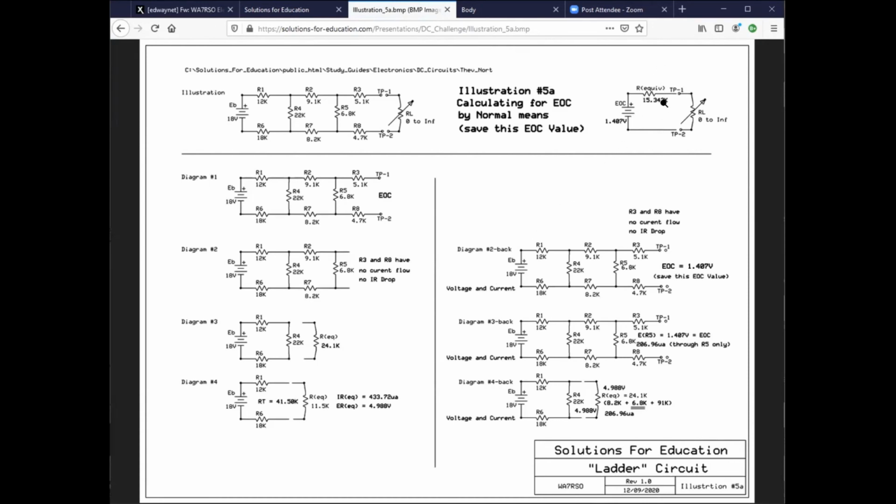We come up to this guy here. Now, what's interesting is I can change this from a dead short to an open circuit. I can tell you what the values are going to be as a result. Put anything you want here. And now we've taken a complex circuit, this whole guy over here, and we have reduced it to very, very simple parameters. And we can project real quick exactly what to expect in terms of current and voltage. Okay. That's the way it works. This is called a Thevenin's equivalent circuit.